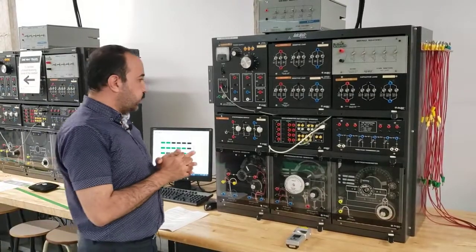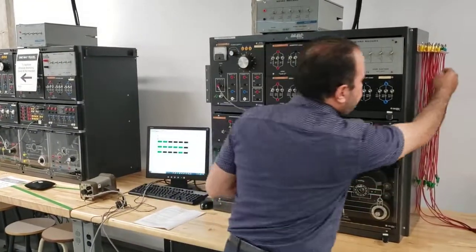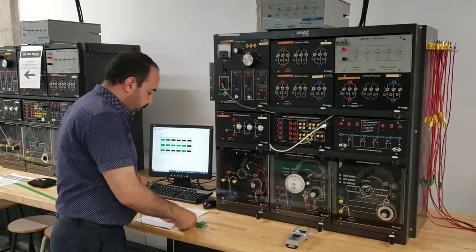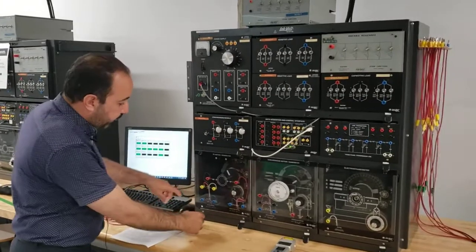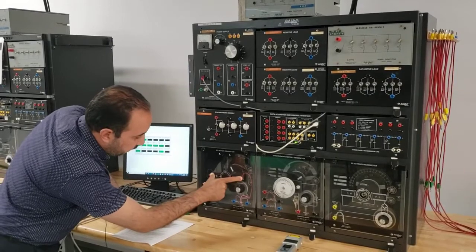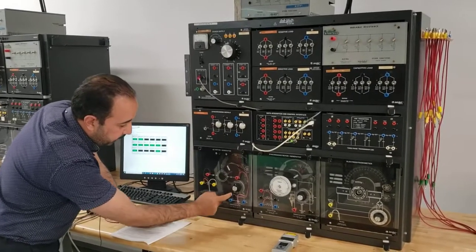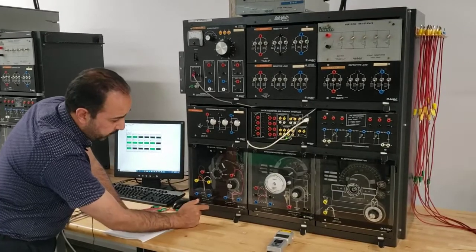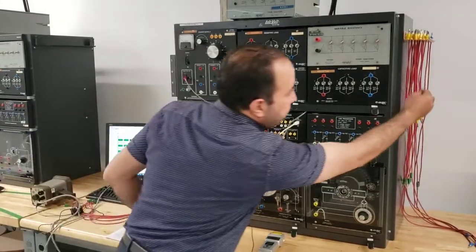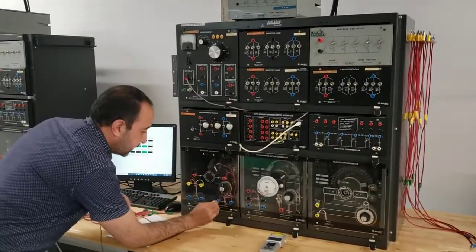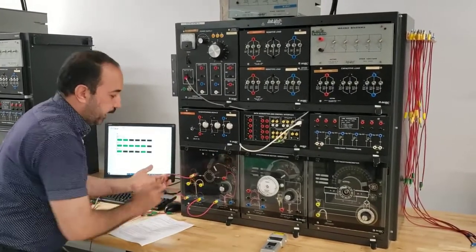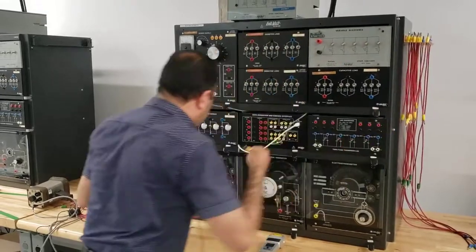So what am I going to do right now? I'm going to connect my synchronous generator, and I'm also going to connect my prime mover. The prime mover, like what you are seeing, will be a shunt DC motor, so I will connect this in parallel with this. But I would like to adjust the field of the DC motor to adjust the speed, so I will use the rheostat for doing that. So I will connect this in series, and then this will be connected in shunt, or in parallel.